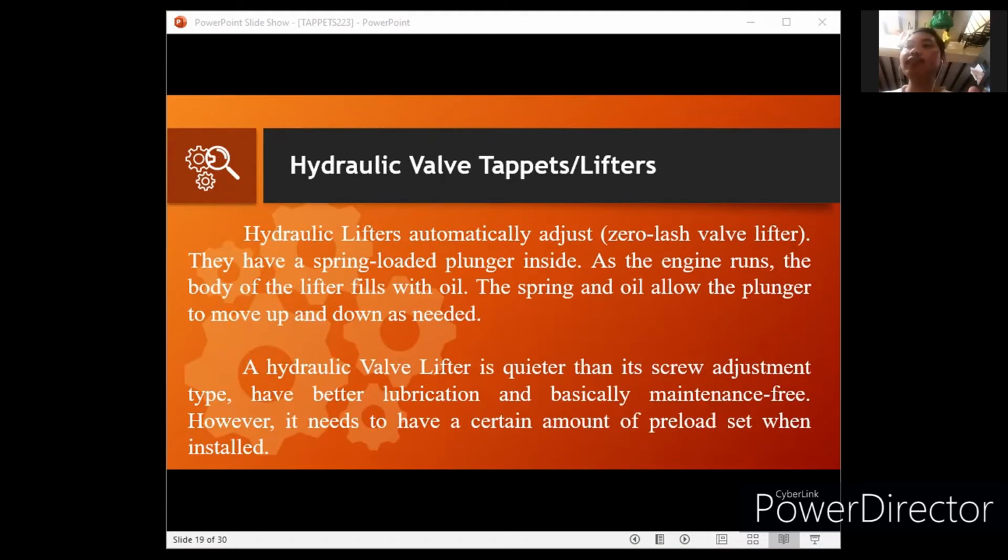One other reason the hydraulic lifters are better than the solid lifters is because solid lifters usually expand thermally during operation. That's why a certain amount of distance is preset to accommodate that expansion. For hydraulic valve lifters, that is no longer a problem since oil flows and moves around the inside of the hydraulic lifters, ensuring that a set temperature is always kept.